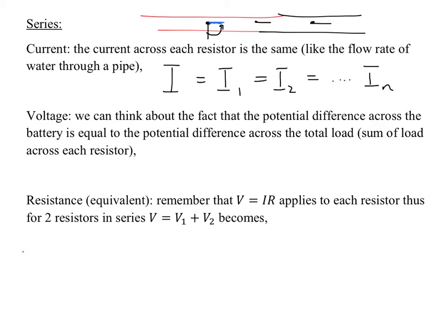So in this case, what we can recognize is that the voltage is being split up to each bulb. Okay, the voltage is being split up to each bulb. A bulb with more resistance will have more voltage used by it. Resistance really means, again, the slowing and using of that energy. So if a bulb has high resistance, it's going to use more of the voltage. What law told me that? What law relates voltage and resistance? Ohm's law, very good. And Ohm's law says V equals IR.